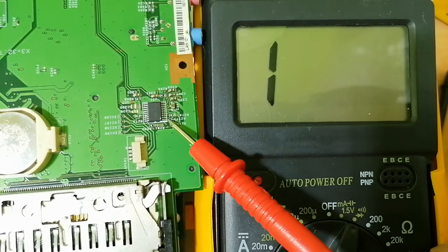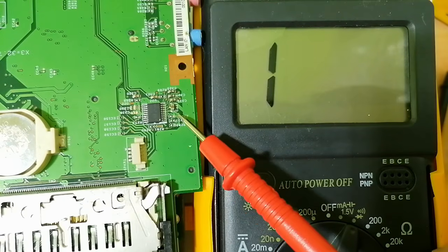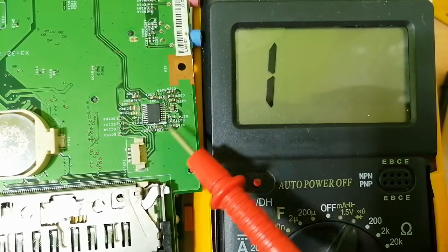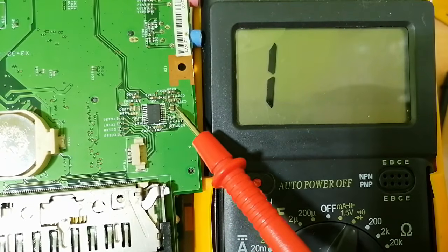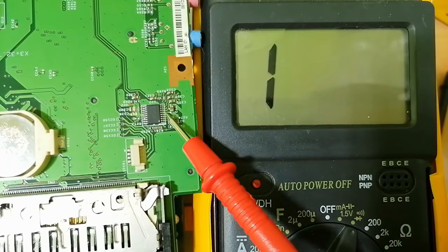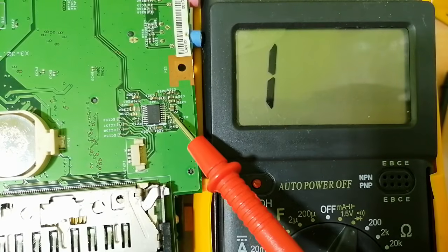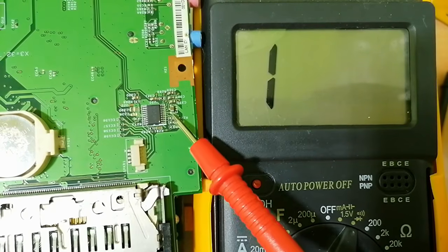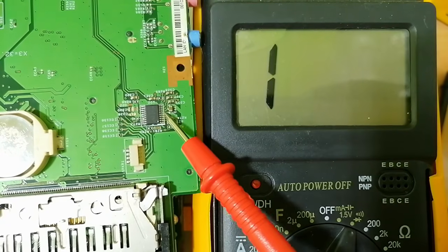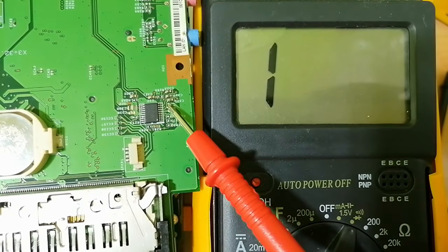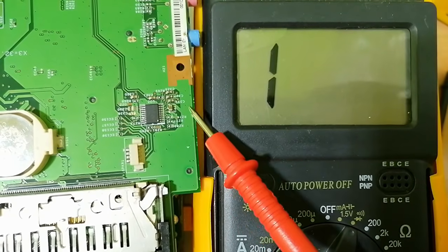Power capacitors are the capacitors that feed the IC with the voltage, like this one, for example. Do you see this one? Here we have a bolded line, means the input for this IC is from here. So this pin of the IC is connected to this capacitor. As you can see, we have the path here, and the other terminal of the capacitor is connected,